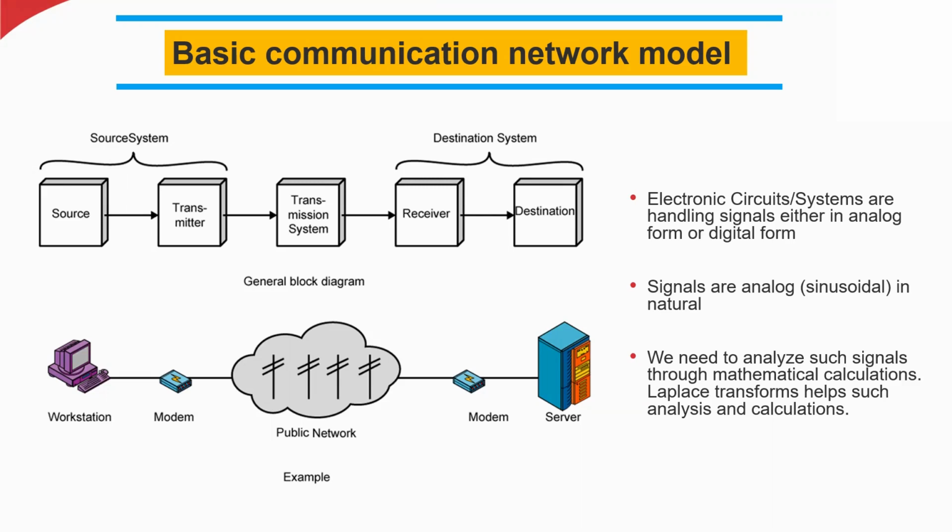For example, I measure the heartbeat using a sensor, or I measure the respiration, the breathing rate. I use some kind of sensor to measure this breathing rate. These signals are really very weak, because this is a very minute change in our chest, for example. So we need to measure that. These weak signals, after we sense them, we must amplify, and we need to filter unnecessary noise from the signals, and then we process them.